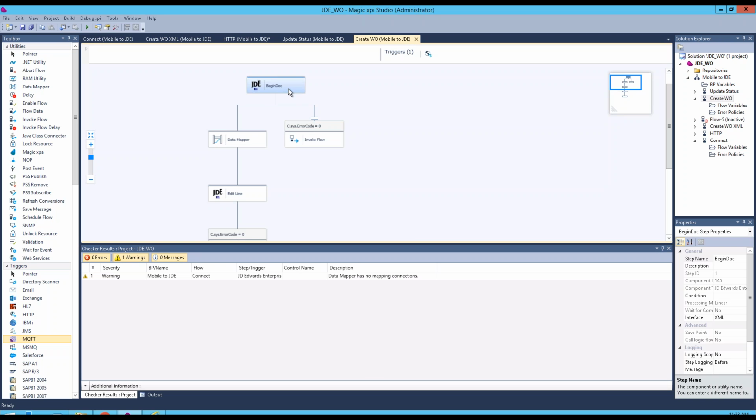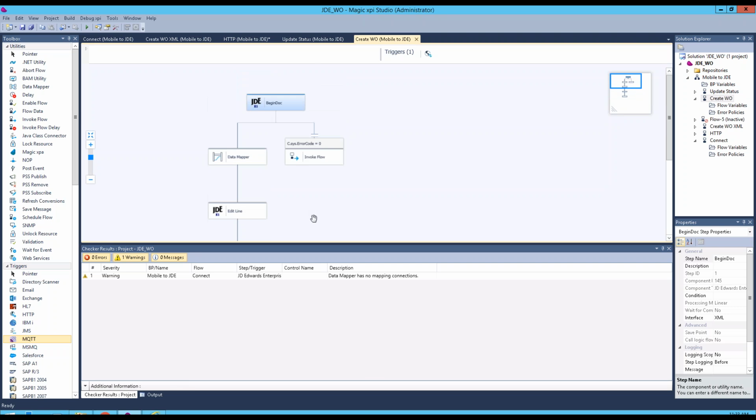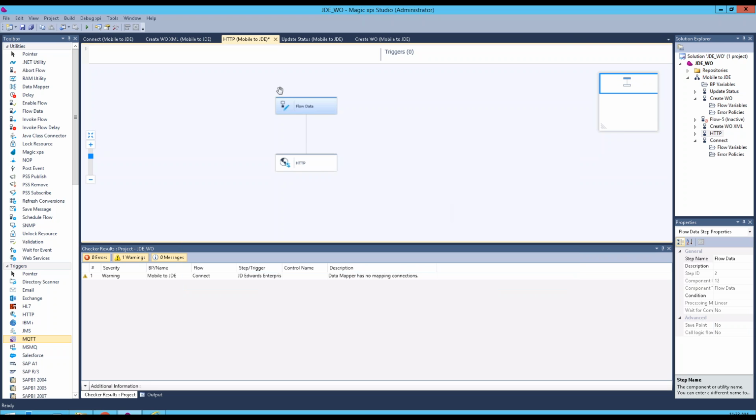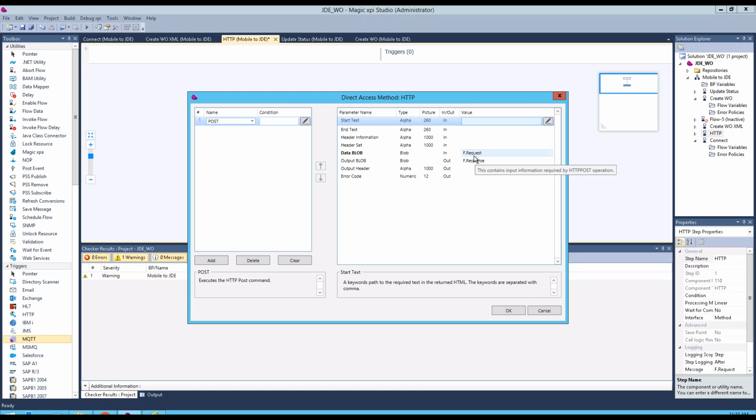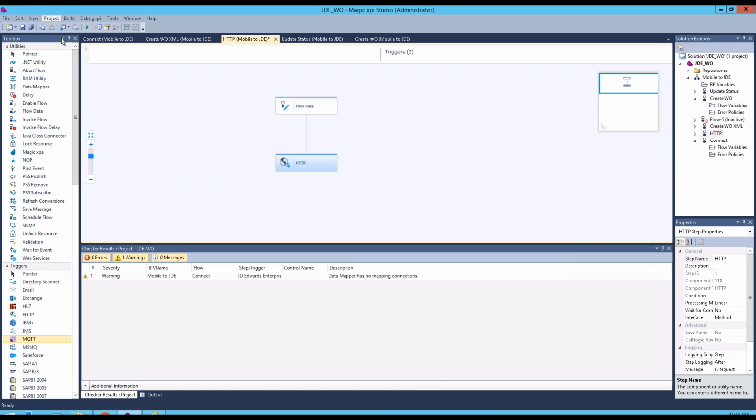Now the application before simply had this flow on the left, and all we did was create the step in JDE, and that was the end of the integration process or the business process. But now, by adding those IoT devices, we're calling a second flow, and what it's doing here is calling our Arduino board. It does this through an HTTP post, sending a set of parameters to this board through its own MQTT server, and as a result, it turns on that light for us when it reaches this step.